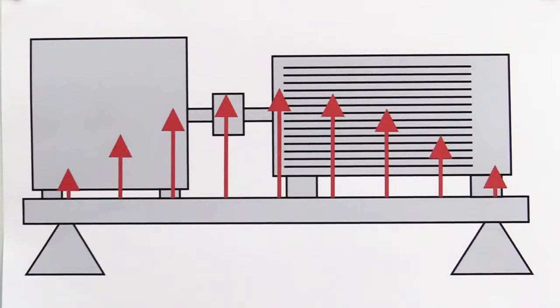We meet with resonance problem usually on the machine frame. When the machine speed is near the frame natural frequency, then we measure high vibrations without visible reason. The maintenance guys usually do all standard procedures like balancing, alignment, bearing mounting check, but vibrations still remain high. The resonance problem is the reason.